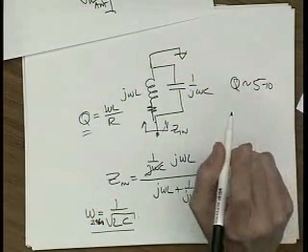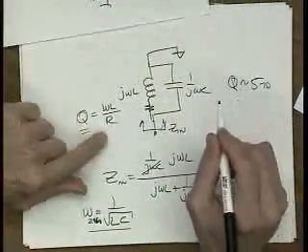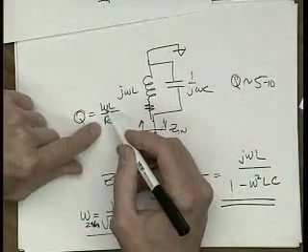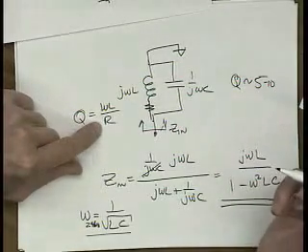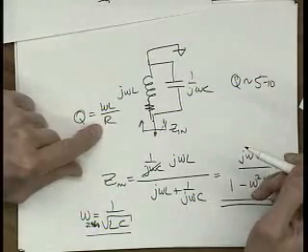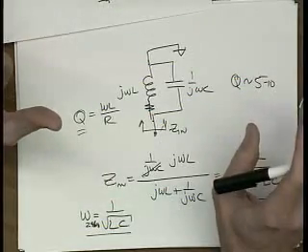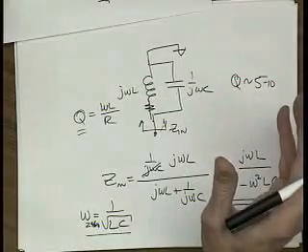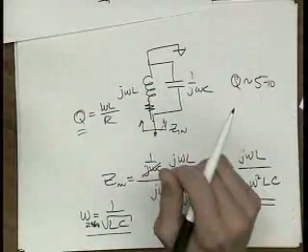Here's something that's really interesting. What happens up at 60 gigahertz? You look at this Q value. If R doesn't really change, omega goes up by a factor of 10, your Q goes up. So actually, at these really high frequencies, these transistors are getting even better. Why would you want to do something at 60 gigahertz? I'll tell you why. 60 gigahertz has a huge amount of bandwidth available. There's 7 gigahertz of unlicensed bandwidth at 60 gigahertz you could do radios in, if you could do that cheaply.